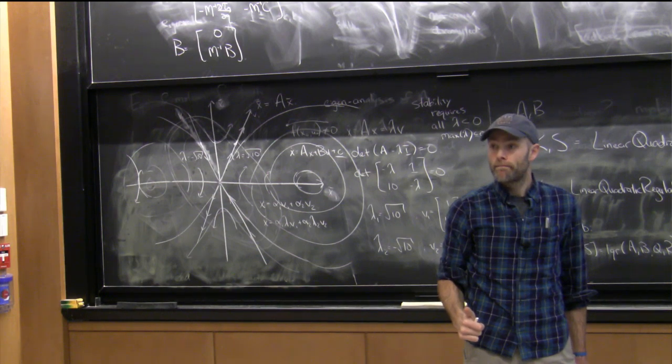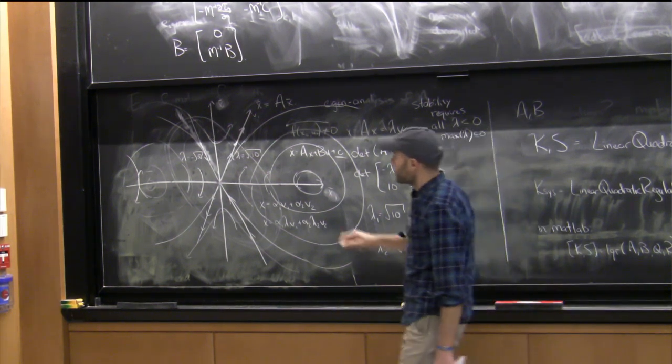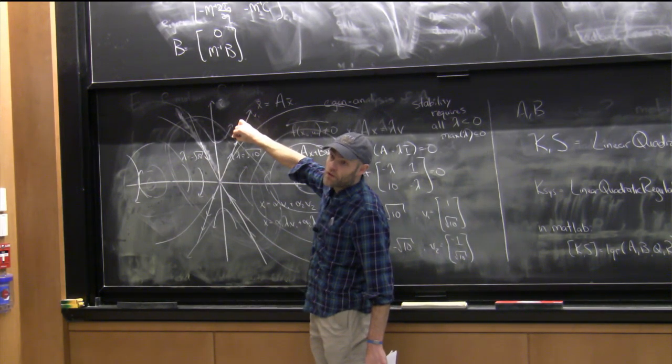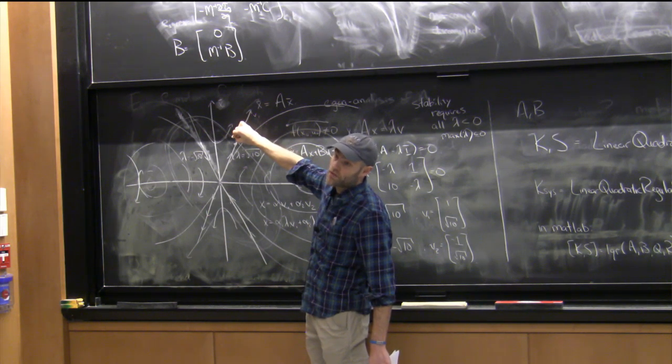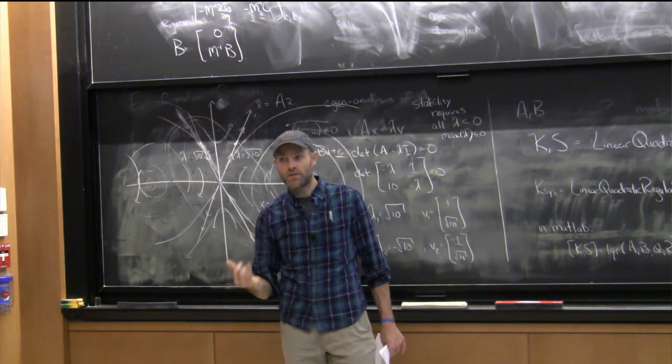Yeah? What's the term for that idea? So the thing we're trying to compute is a region of attraction of the linear controller for the nonlinear system. And we'll use our Lyapunov ideas, and we'll make algorithms that try to find Lyapunov functions to prove, just like we did in the original definitions.